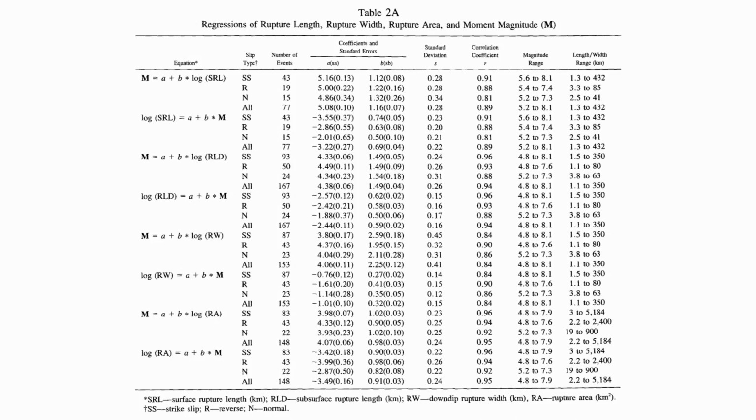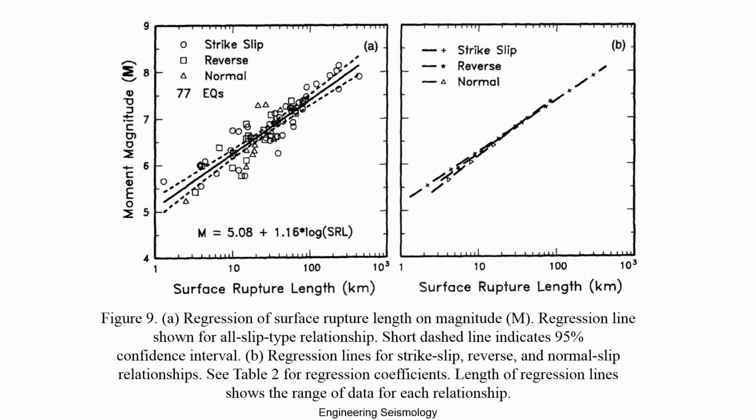So, we take that as a basis. The equation given for the magnitude versus subsurface relation for a particular fault type depends upon the fault orientation or fault type in the region, and is applicable to all faults you can take. Okay. That equation you can take as this one, subsurface rupture length, moment magnitude, for different fault types, and this is the relation you can take.